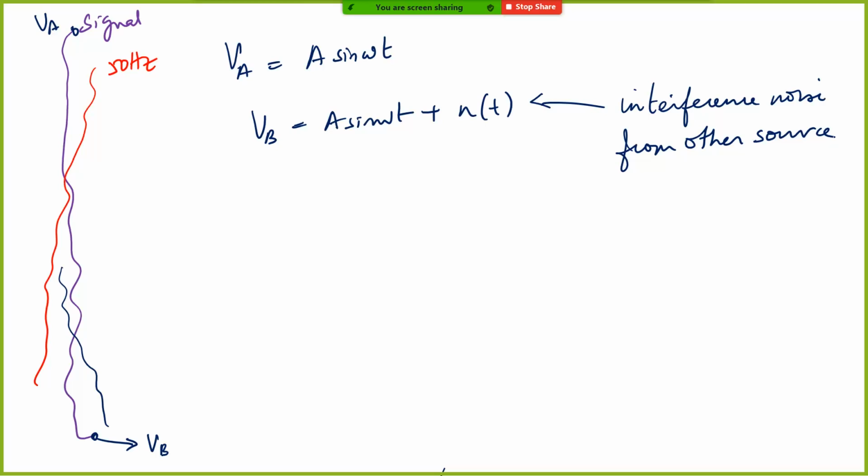So in order to remove that 50 hertz, you will put a notch filter at 50 hertz, to remove the power supply component and then amplify the signal. It's especially done in biomedical signals because the bandwidth of biomedical signals is very low. If you look at ECG signals, it would be less than 30 hertz, something like that. Even EEG is very low, right? So that is the reason, and 50 hertz is a big interferer.